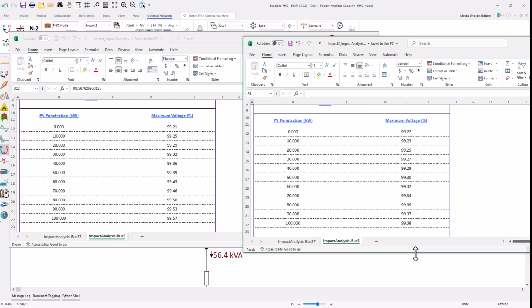And because nodal hosting capacity considers all of the buses individually, in a sort of superposition way, when you combine them, you cannot install the same level at all buses. So you may have your own planning parameters and factors where you can take the nodal hosting capacity results, downsize them to a certain degree, and provide that as minimum and maximum for your stochastic optimization. All of this is to say you can really narrow down the results if you can use one piece of information, make sense out of it, and plug it into another as an input.